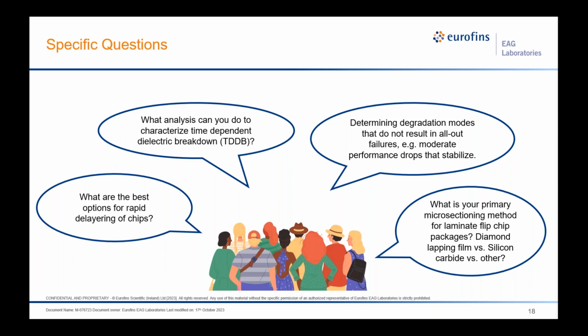Now, with some of the advanced node technology, like FinFETs and things that are lower than 10 nanometer, the layers are nanometers thick. So it may be impractical for us to do a really great layer-by-layer deprocessing, and that may require something like a plasma FIB, or PFIB, to perform that deprocessing. So in a sense, the speed at which we utilize these techniques depends on how pinpoint it is, what kind of technology it is, what layer we think it is, and how wide of an area we need to inspect.